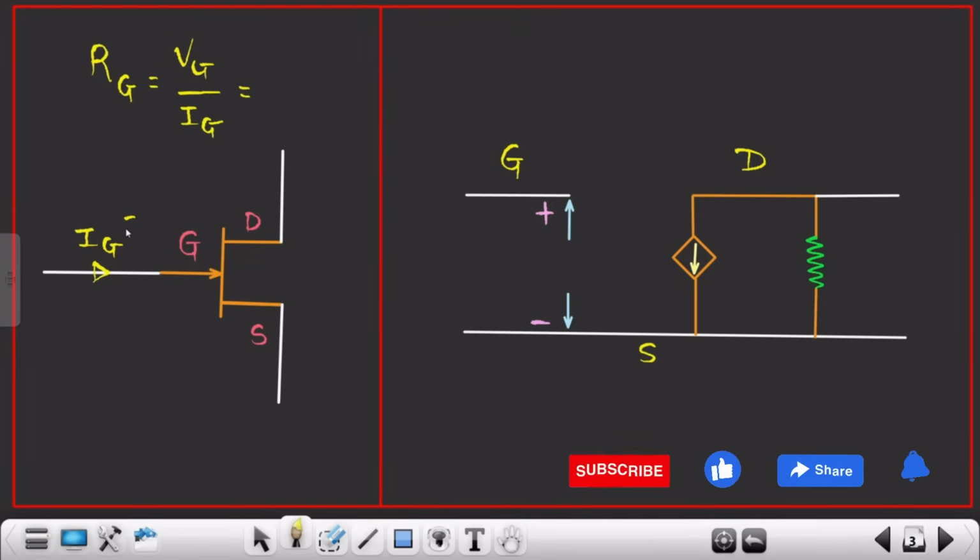This is what we know. And why is IG 0? Because the gate and source terminal are connected in reverse bias condition, and my IG is 0. Whatever the value might be present over here, let's suppose that is X, my resistance RG would be infinite. I hope you are getting this particular point.